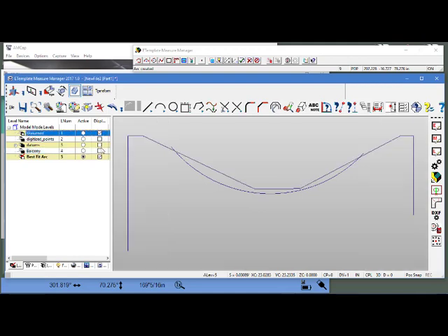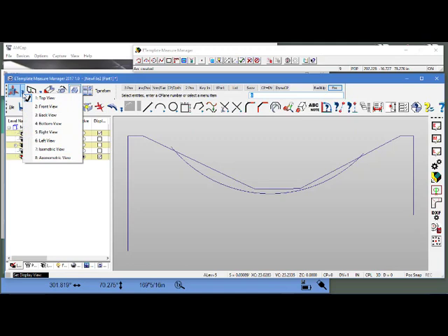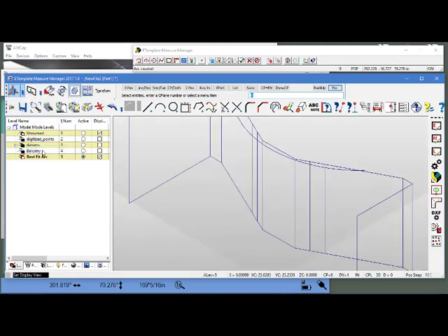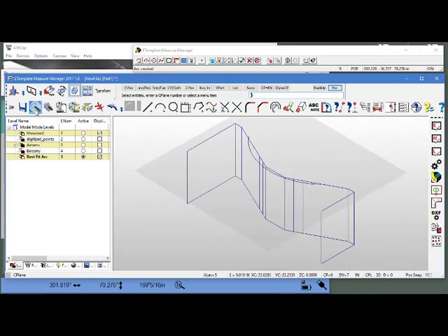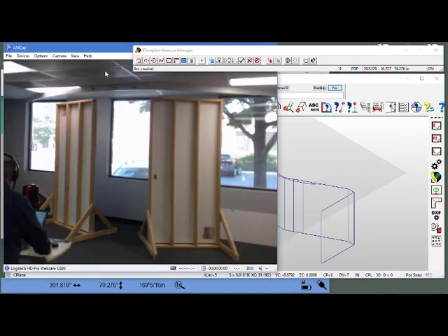All right, let's put this again in an isometric view. Make everything visible. Now what I want to do is extrude just this arc for a cap that goes on it. And since we made the construction plane that we created the arc on the ceiling, I'm going to shoot the bottom of this balcony, and it'll create this piece.